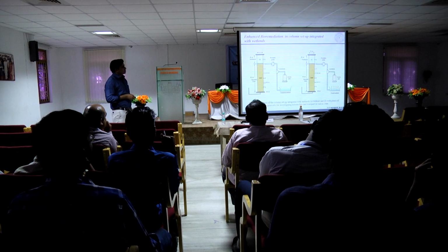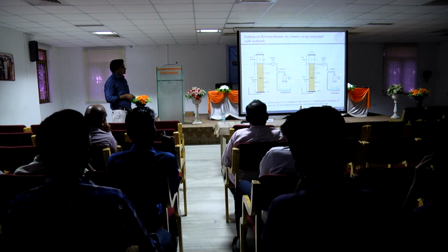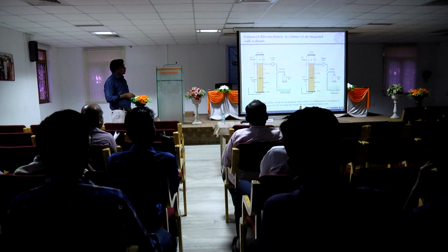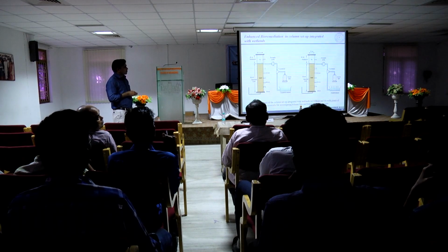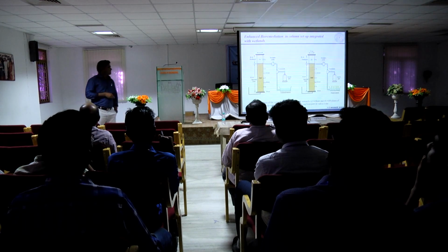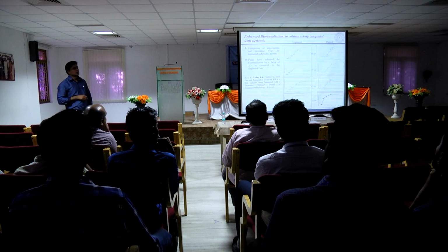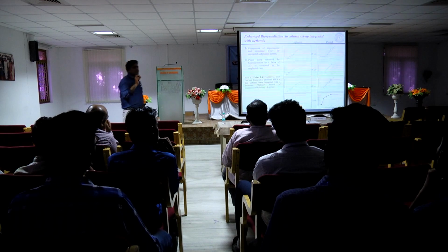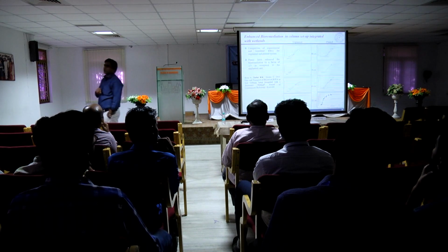Polluted water was coming from this stock solution here, and the water flowing from this treatment wetland was supplied at the top of this column, and it is moving vertically downward to show how this polluted water moves into the soil. Then we are seeing how these contaminants are moving. These are the different ports from which samples have been taken. The dots show the analyzed samples, and the solid line shows the numerical model results.